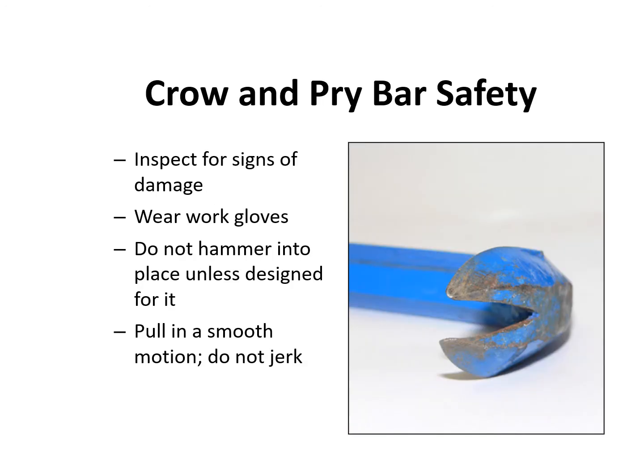When using a crow or pry bar, inspect the bar for any signs of damage and cracks. Wear work gloves to protect your hands from metal spurs. Do not hammer between objects unless the crowbar or pry bar is designed to be hammered into place. Pull on the pry bar or crowbar in a smooth motion.